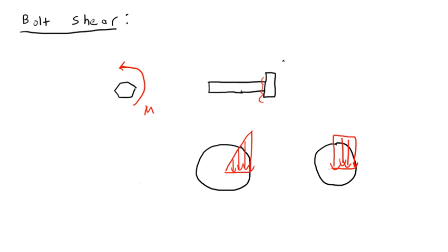So if we're using our ridiculous 50-foot long cheater bar or something like this, the grooves of the bolt are back here, right? And it's actually secured back here. If I apply an enormous force here, an enormous moment here, it needs time for that moment to make its way all the way back. And once it does, yes, it will release the moment by turning. But if there's not enough time for that, we're talking fractions of a second here, if I apply that force too quickly, then that's where you really get in trouble.